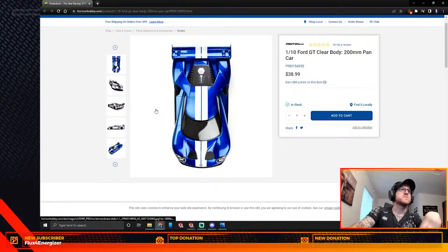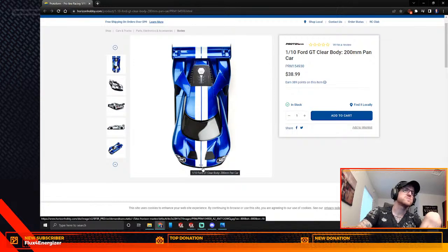So the body itself, we can see it comes out a little bit. It does not have a full complete radius, but it's somewhat close. So we're going to have to reduce that flat size and make this spline radius a little bit larger. We'll make this side a little bit flatter.